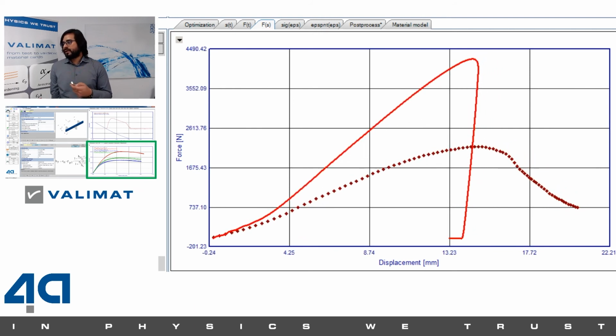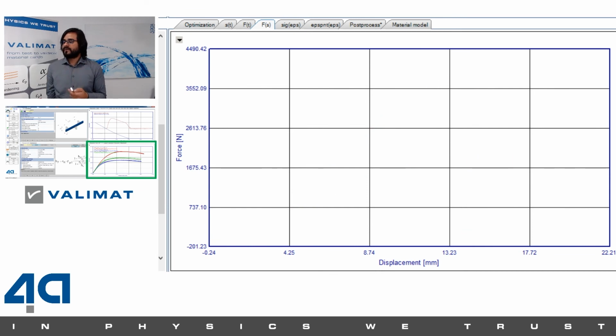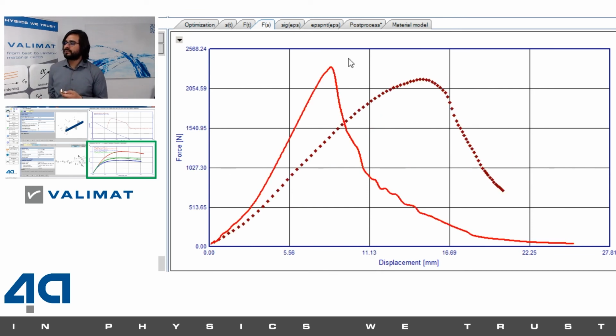And then we see what the influence is when we have failure. If we go into the puncture test with the failure setting that I have used, see, we have failure. The force peak matches quite well. The behavior is stiffer compared to the test data because of the lack of tension. This is basically the Autofit workflow that I have gone through here.